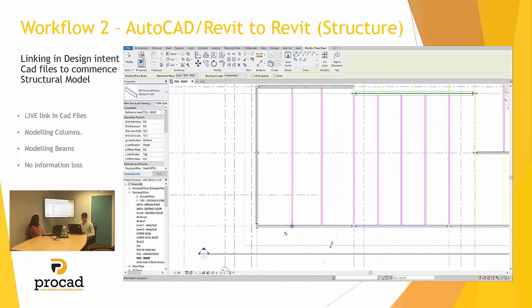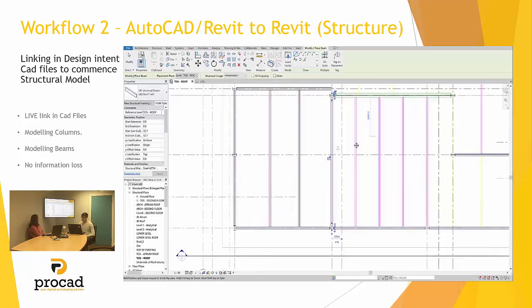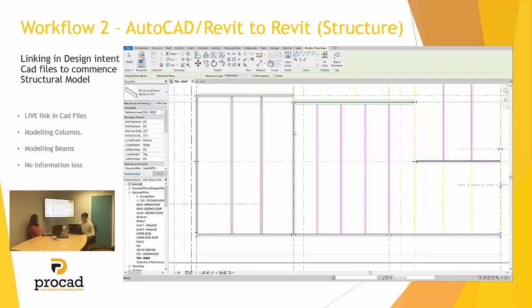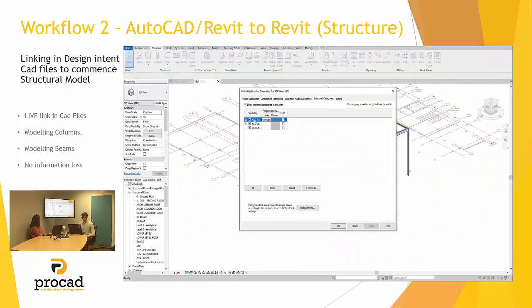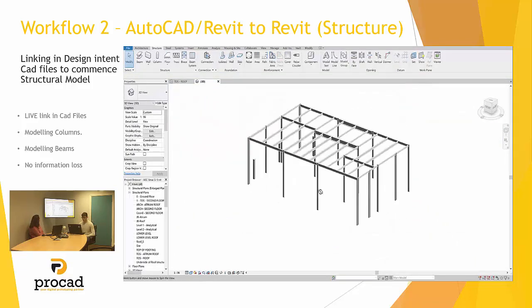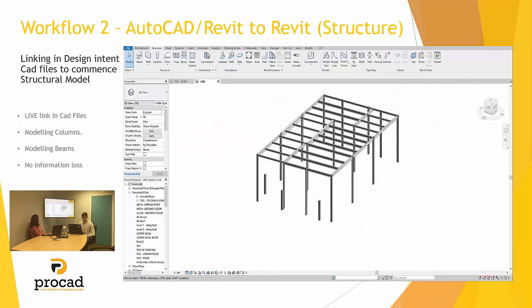It's actually a good thing to note that when you are working with these CAD files and linking them, you're always working with the latest. So when you go back into your visibility graphics, you can turn off the CAD files and you can see then you have a 3D structural model. So to hand you over to Ger now to show you how you coordinate the structural model with the architecture's model.